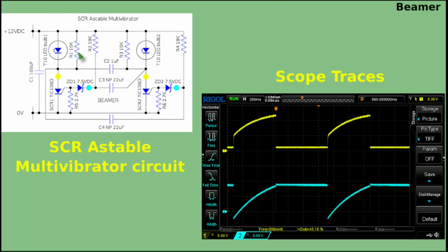So it's a kind of extension to one of those three options. But those two 10K resistors are in there just to make sure that when this is asked to be conducting, the device at a minimum will conduct via this resistor here. Because bear in mind that an LED is not a fixed resistor. In fact, below the current which lights an LED, the resistance is actually quite high. It's only when the LED starts conducting that the impedance drops. So that's why that little important resistor is there.